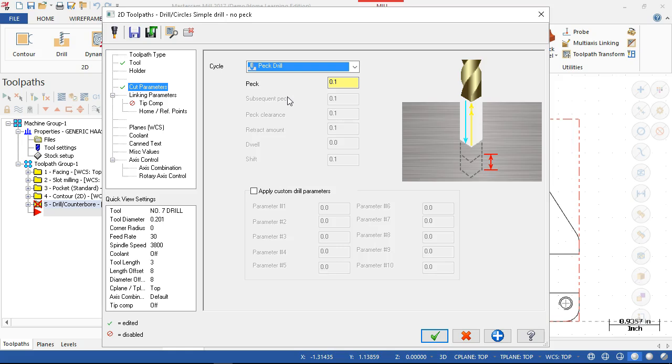I thought a reamer makes the hole a very specific size. It does, so it shouldn't be straight. It shouldn't. Doesn't mean it won't. All right, so if it's exactly on size and you've loaded it, and depending on tool holder, how much protrusion you have, tool deflection, any number of possibilities, it could drag. I would just soon have it.